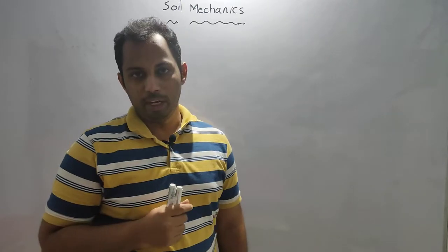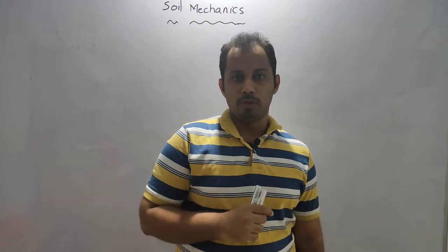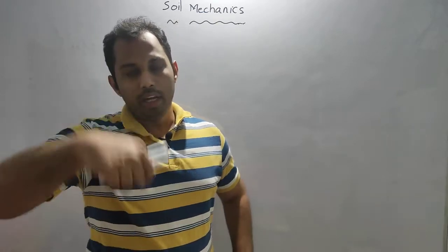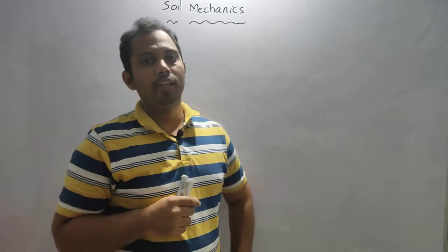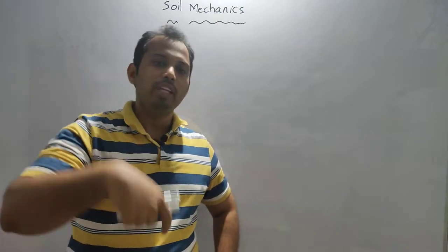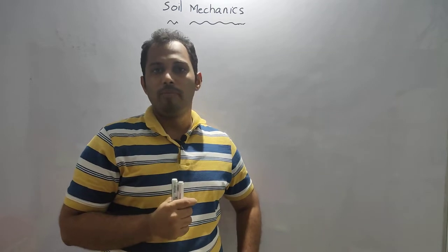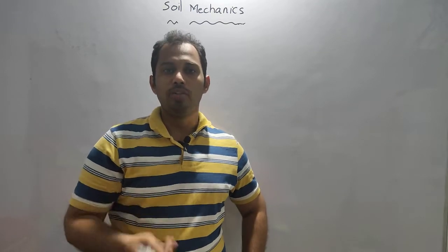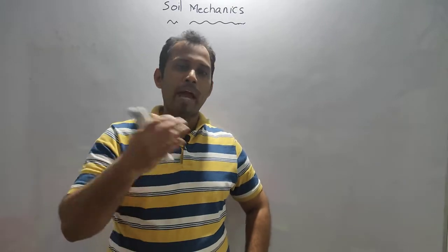Why? I will explain. See, how do we generally apply load on soil? In general, we apply load on soil vertically. The load applied on soil is vertical in nature only. Always we apply vertical loads on the soil. Have you ever seen application of a horizontal load on a soil strata which is below the ground level? Okay, sometimes we may form embankments.